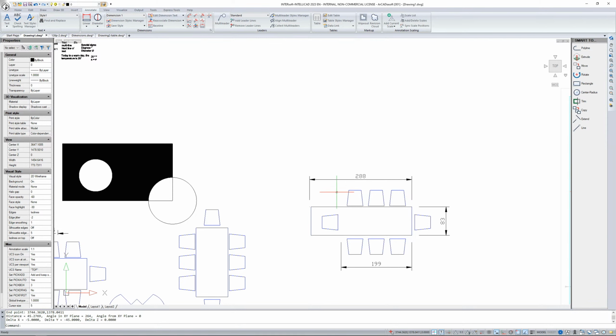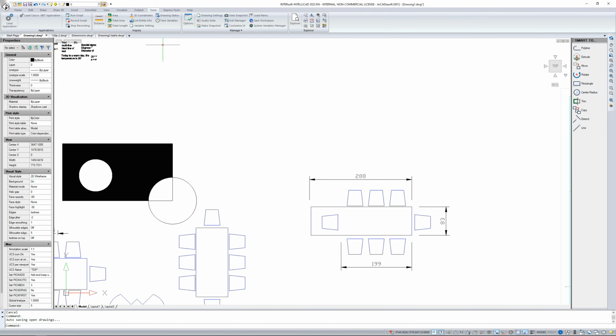Please note, on the drawing, nothing has changed. Only in the command area at the bottom of the screen, the distance appeared. So the length of that part that I indicated, the angle and the area on which it was entered, and how much is X and how much is Y if I need that information. You can check such parameters using the distance option.